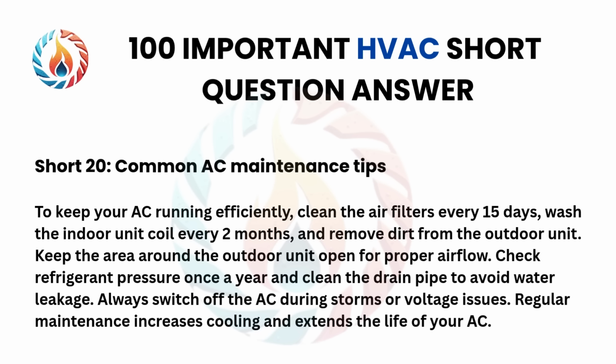Check refrigerant pressure once a year, and clean the drain pipe to avoid water leakage. Always switch off the AC during storms or voltage issues. Regular maintenance increases cooling and extends the life of your AC.